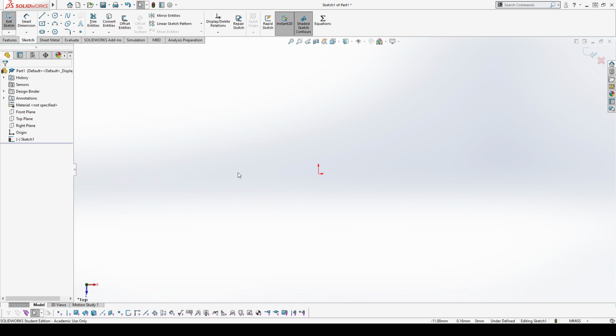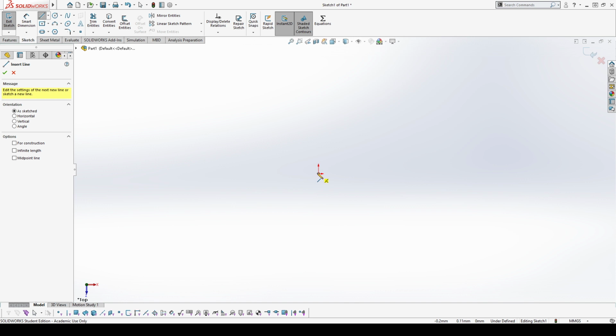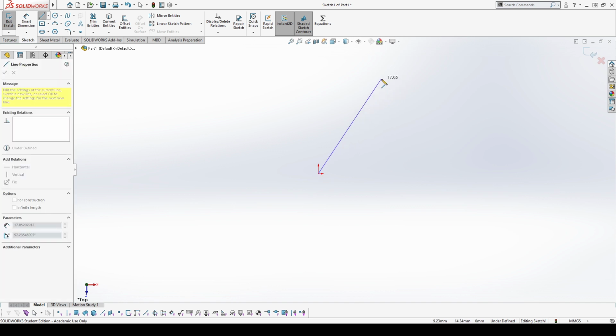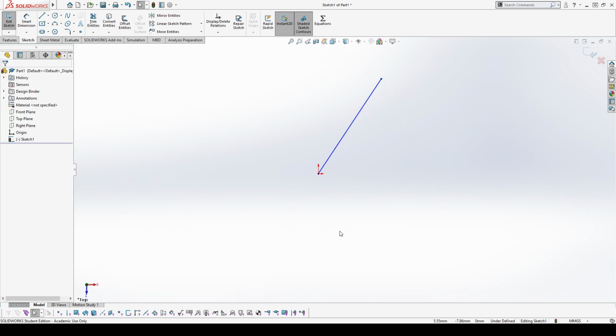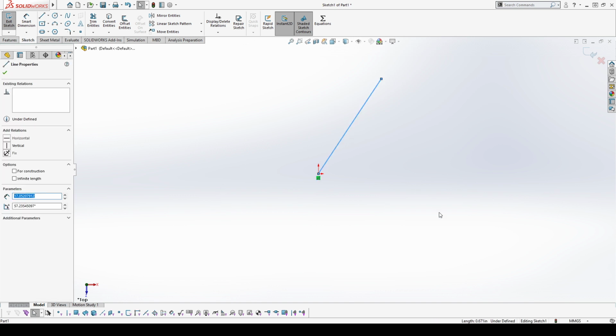Geometry, or we turn that into geometry by dimensioning each of those vertices or edges or the faces and how far apart they are. Or also, if they're parallel or anything like that. So usually a good rule of thumb is to try and add relations first and then dimensions. And we'll start to look at what are the different kinds of relations that we can have, just for a simple line. I just drew this line, it's pointing arbitrarily out in space. I'm going to click on that line to bring up its properties.